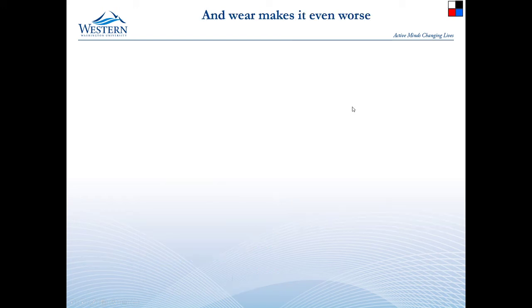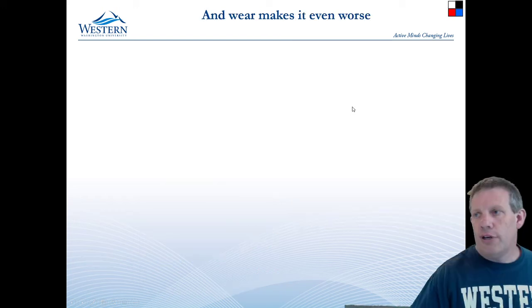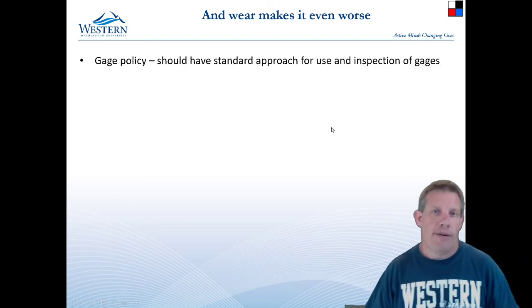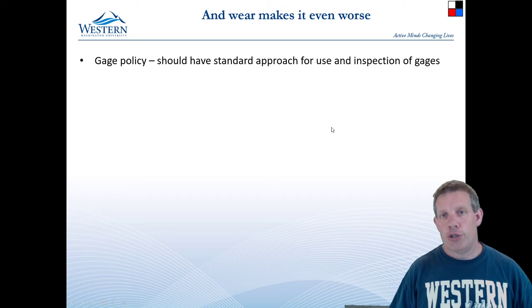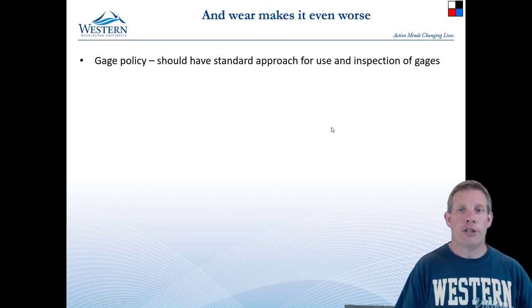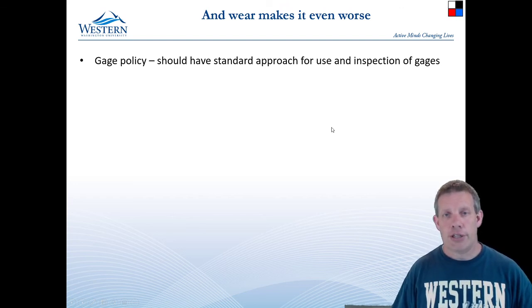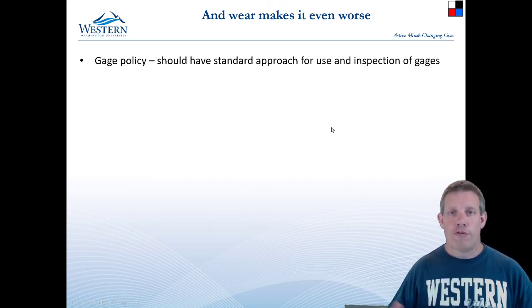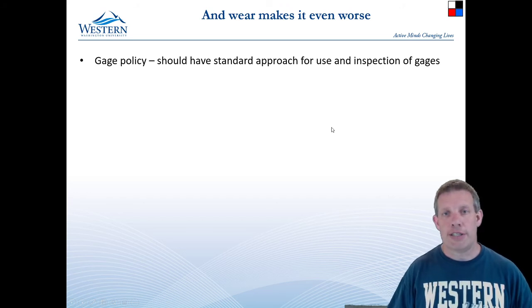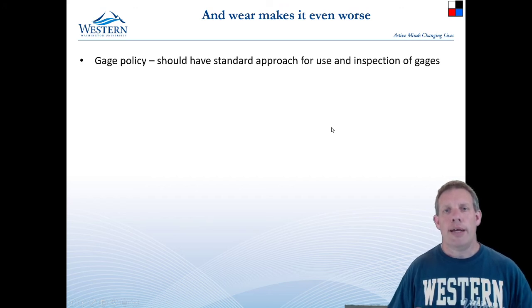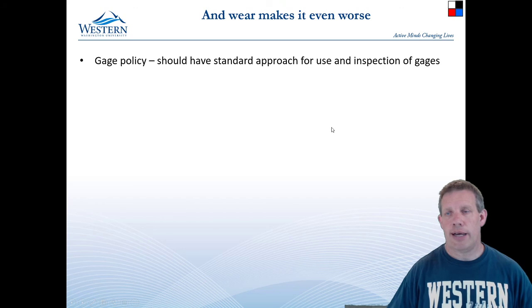Well, in whatever company you're in, your company needs to have a gauge policy, and that gauge policy should cover things like, are you using unilateral or bilateral methodology of applying tolerances to your gauges? It would also have things like what percentage you are using for working gauges, inspection gauges, and master gauges. The 10, 5, and 1% are kind of industry standards, but they are rules of thumb. They are not a written standard. And so your quality plan would need to cover that kind of thing.